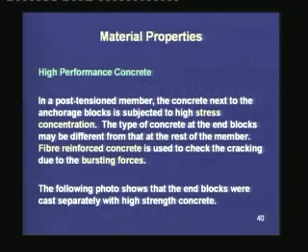In a post-tension member, the concrete next to the anchorage blocks is subjected to high stress concentration. The type of concrete at the end blocks may be different from that at the rest of the member. I told last time that the anchorage block actually bears against the concrete, and right next to the bearing plate, the concrete is subjected to a high stress concentration. This leads to some transverse forces which are called bursting forces, and these forces can create cracks within the concrete.